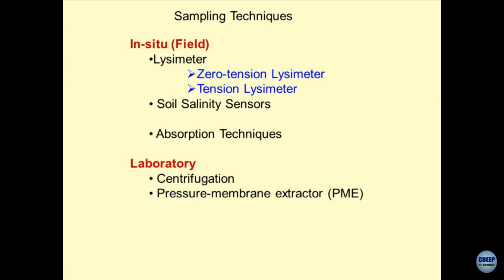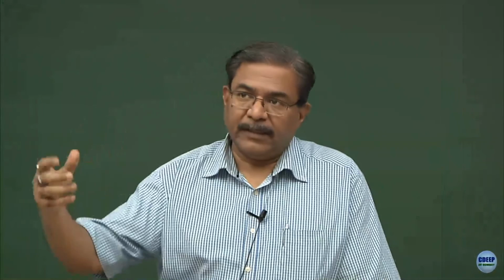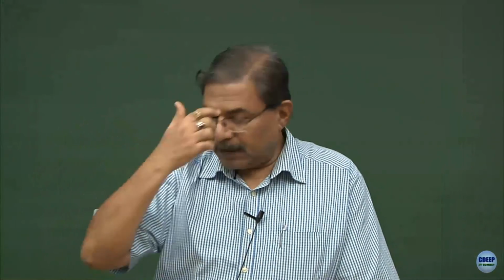and how the pore solution sampling can be done. Apart from this, I can use some fluid displacement methods also, by pouring a fluid of a certain density which is higher than the density of the pore solution in the soil mass, and then by a density separation technique I can force the lighter fluid to come out, but these are very tricky methods.